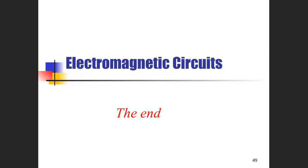Once again, remember the permeability mu, which changes with the current. In the analysis of the magnetic circuit, the key is determining the mu. Therefore, you can determine the reluctance and you can determine the inductance of the circuit. That's the key issue. Do not forget that.